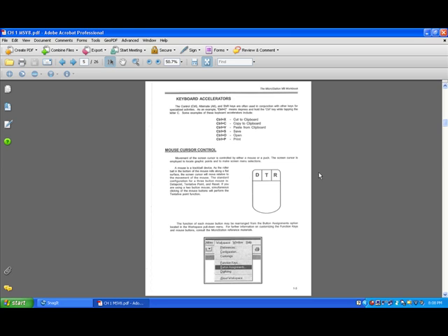Tentative is the ability to set a tentative point, but you're not actually putting the point there. Sometimes we use that when we just want a place marker. And as we get into the next session, the next class, we're going to utilize that to do some things called offsets and whatnot, so don't worry about it too much. You can also use the wheel by default as a zoom in, zoom out command.